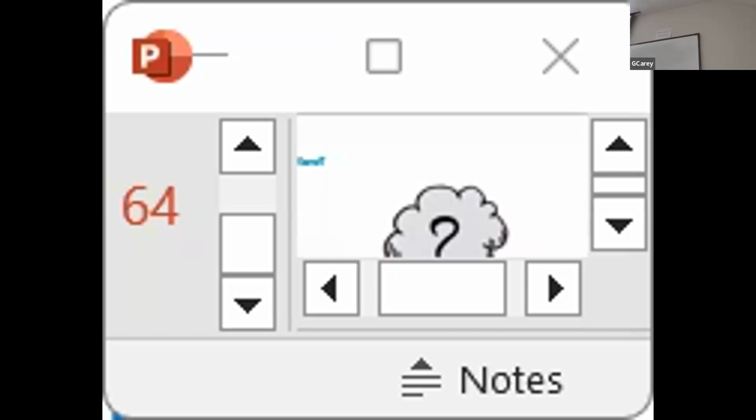So one of the first things they did is they put three-way valves in. What would be the benefit of the three-way valve? Yeah, constant flow. It didn't change, whether the valve was on the terminal unit side or the bypass side. What are these balance valves for? Why would they have needed them? So that no individual system.